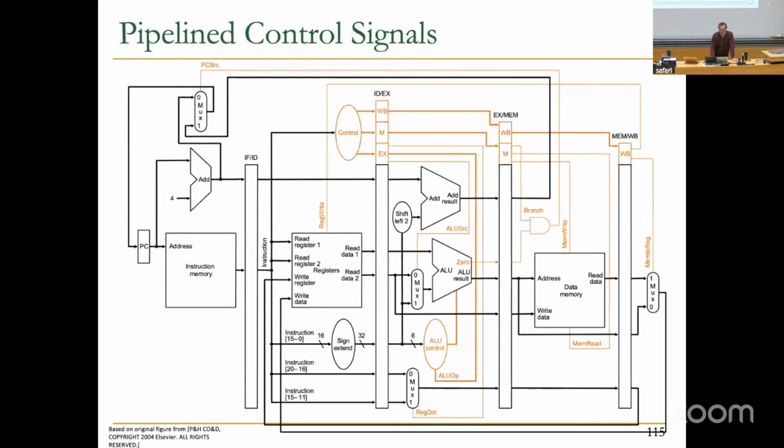It depends, basically. So here, this is actually the same single cycle processor divided into pipelines, and the control signals delayed as to when they're really needed. For example, the execute stage needs ALU source, these multiplexers over here. They need to be controlled. And these control signals are generated in the previous cycle, stored in the pipeline register, and used in the next cycle. These are the control signals that are needed in the execute stage.